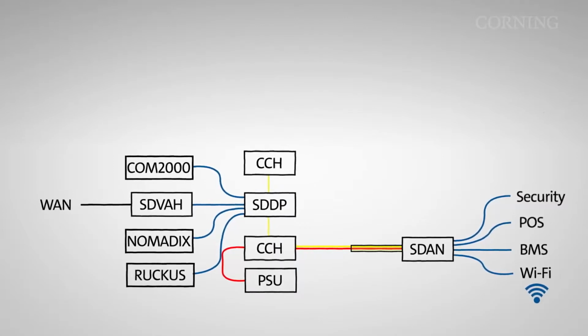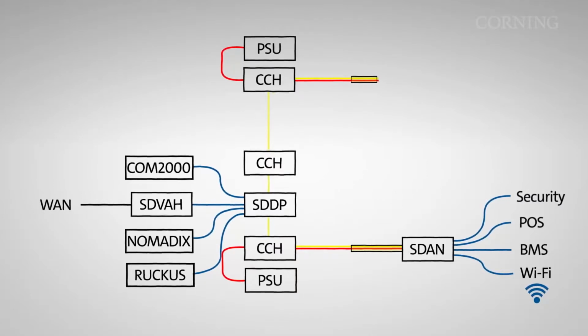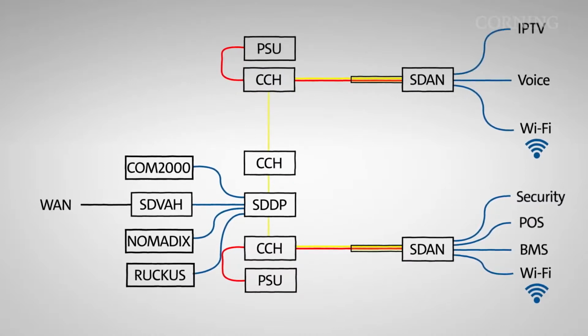Then out of this software-defined data plane, we have gigabit SFPs, which are going to be serving ONTs in the guest room. So this is going to be a simple patch cable to our outgoing fiber, and I'm also going to be injecting power from the PSU. So I'll have a copper jumper just for power, jumping to the same patch panel. Then out the back, like we discussed previously, I have composite cable, which will go to the guest rooms, hitting a software-defined access node for my connectivity to Wi-Fi, voice, as well as video services.